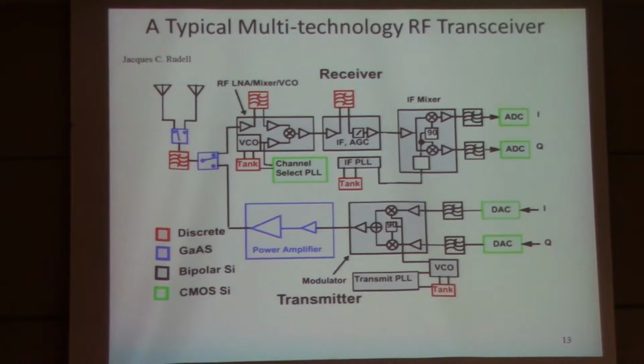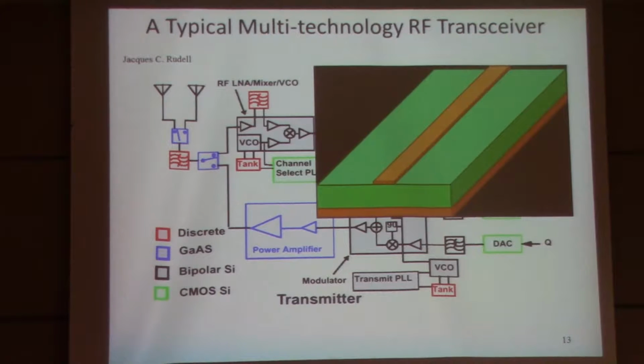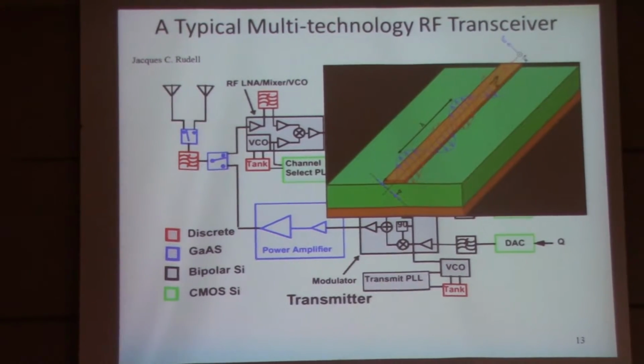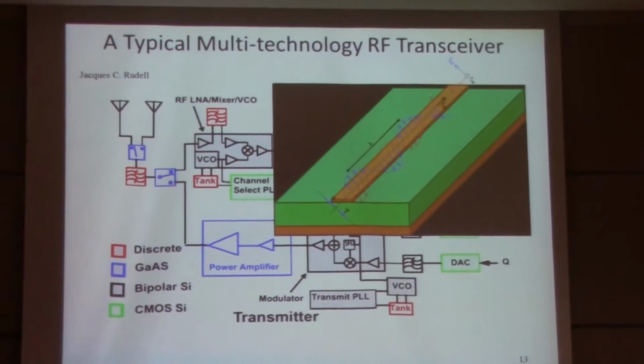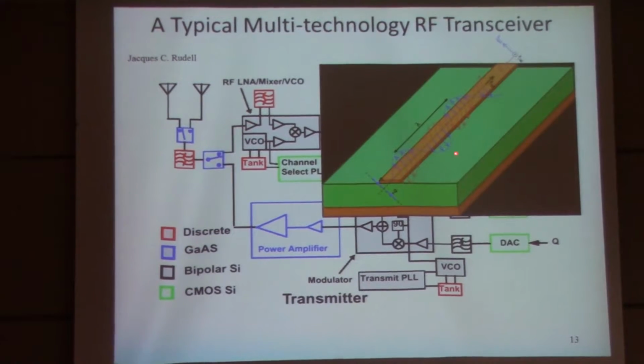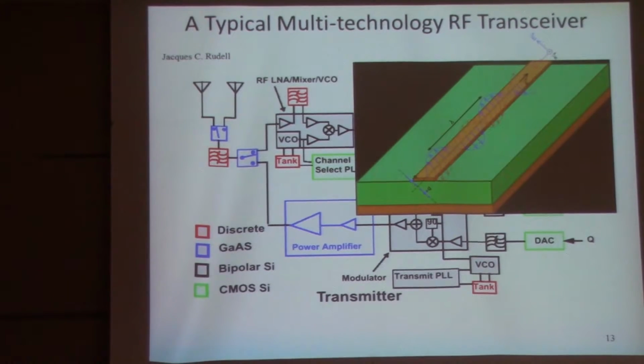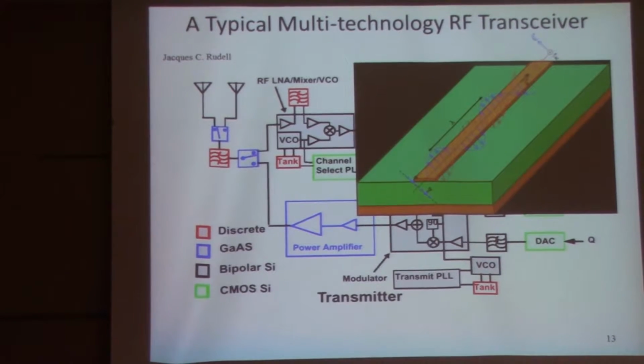And the problem associated with this circuit when you want to design it is that very often, okay, the frequency you are dealing with is very high. I just mentioned that. So the wavelength of your signal is comparable with your dimensions, with your circuit or device, even device dimensions, okay? And because of that, you can't use the traditional DC circuit concept to design your circuit.